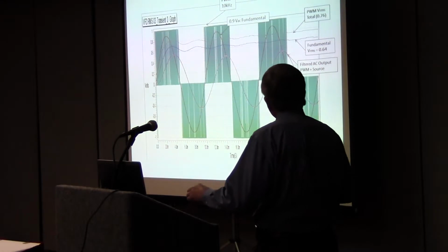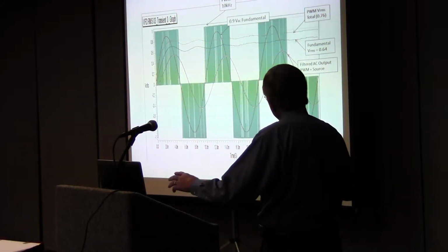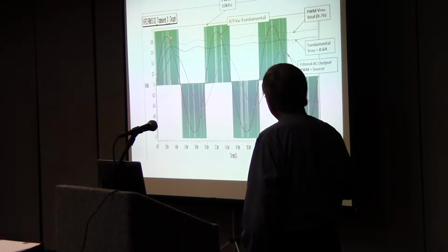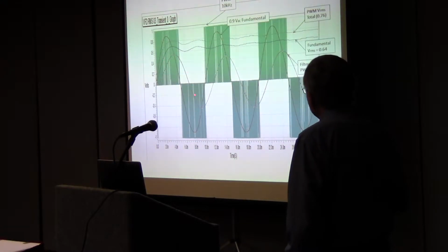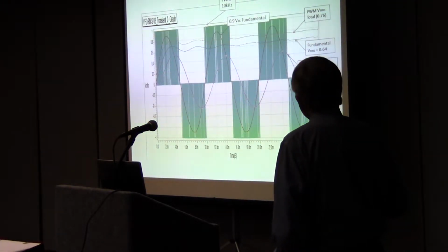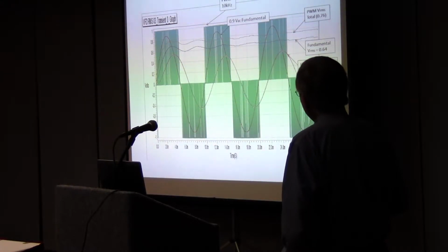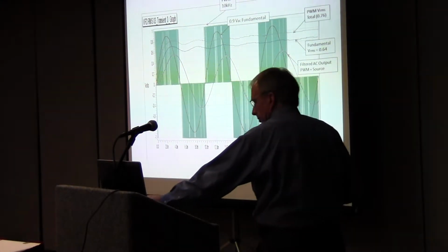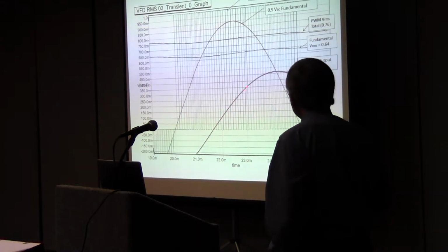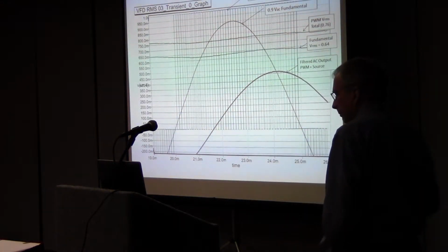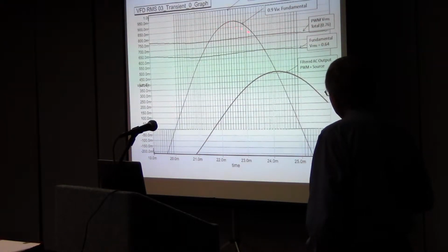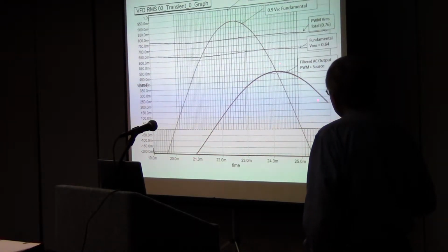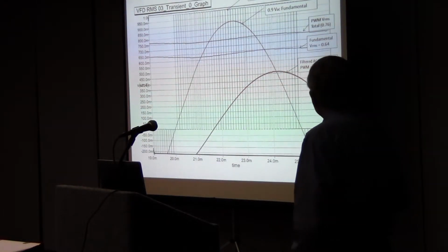And if you want to, it's synthesizing a 60 hertz wave, which is basically this wave. What we did here was we put that through a low pass filter, and this is what we get out. So that's what the compressor is trying to run on. And I know you can't see it here, but there's actually two waveforms there. You can kind of tell here it's a little bit broader line. We actually filtered this waveform, and then we also put this signal that we created through the same filter, to prove that they do indeed coincide.